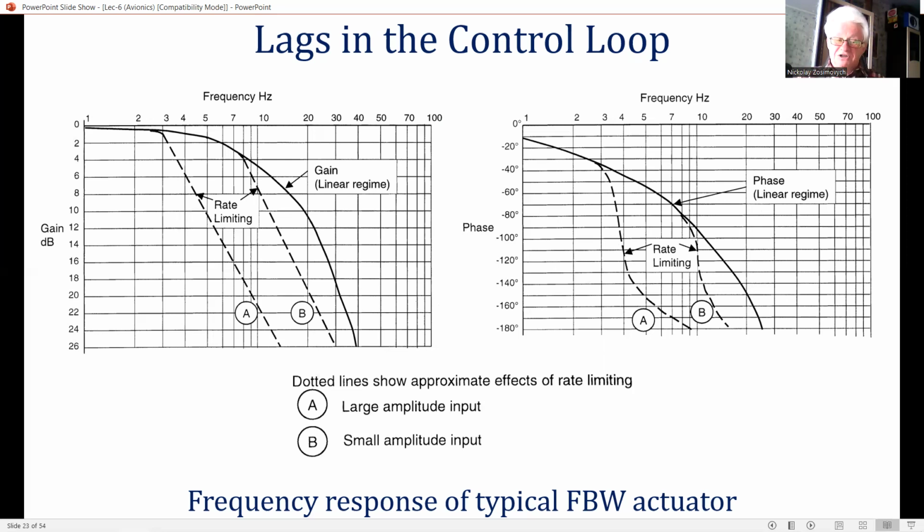Solid-state micro-machined quartz tuning fork rate gyros also have a bandwidth in the region of 60 Hz. The phase lag at low frequencies with such sensors is fairly small, about 5 degrees at 5 Hz, but may need to be taken into account if there are higher frequency structural resonances present.